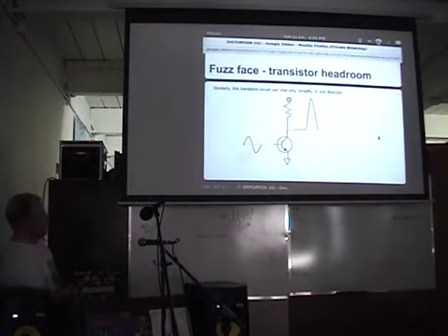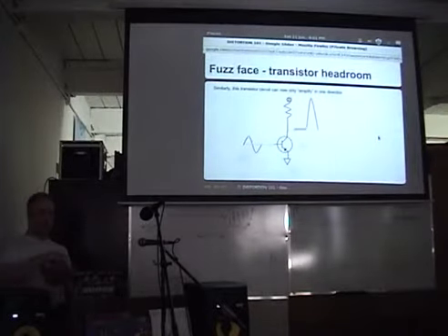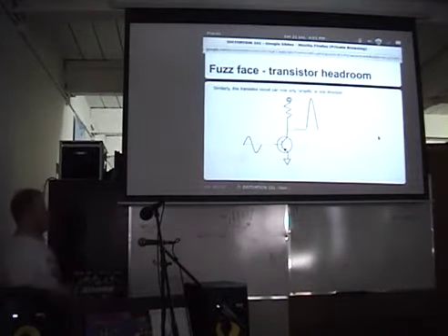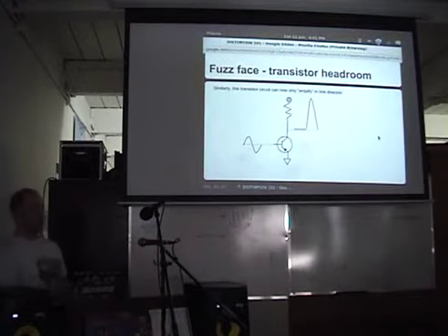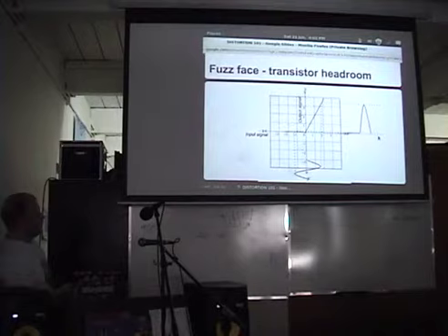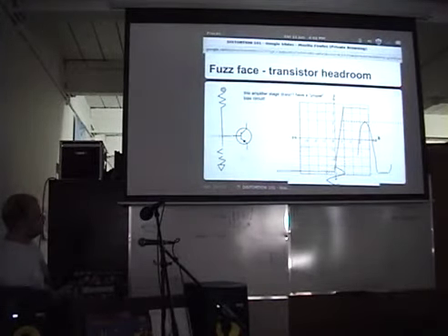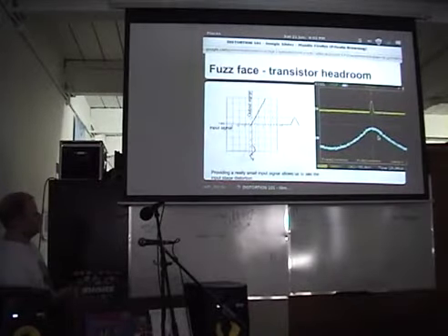As soon as you try to drive it any lower, you just get no signal anymore. So this input stage, which is supposed to be a faithful representation, a nice current buffer, is actually distorting the signal by an extreme amount. And that's what the transfer function approximately looks like. Again, the bias isn't quite there.